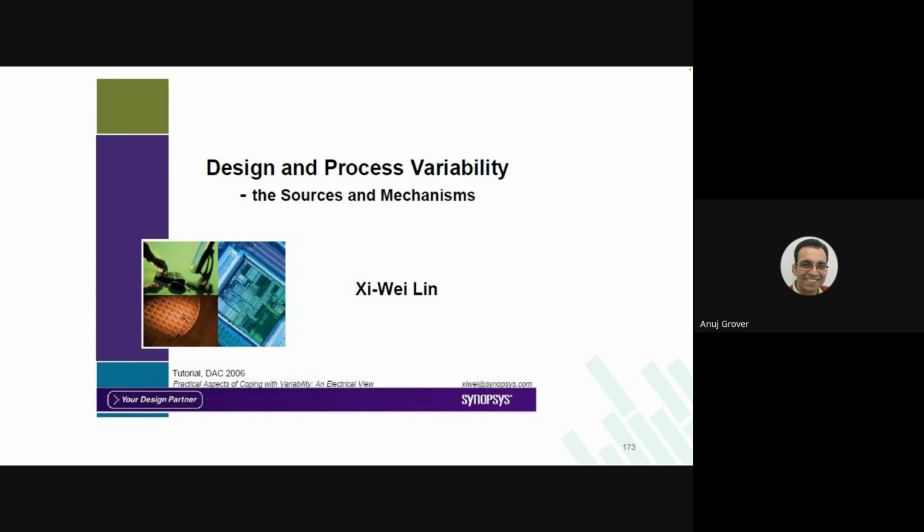One thing that I want to establish with all of us is that there are two kinds of mismatches. One are systematic mismatches. For example, N well proximity effect is a systematic mismatch. You can model it. He asked me, how will the VT change? You can easily model it. You have the VT equation which includes Na as a part of it. Is it not? In the VT equation, Na is one of the variables there.